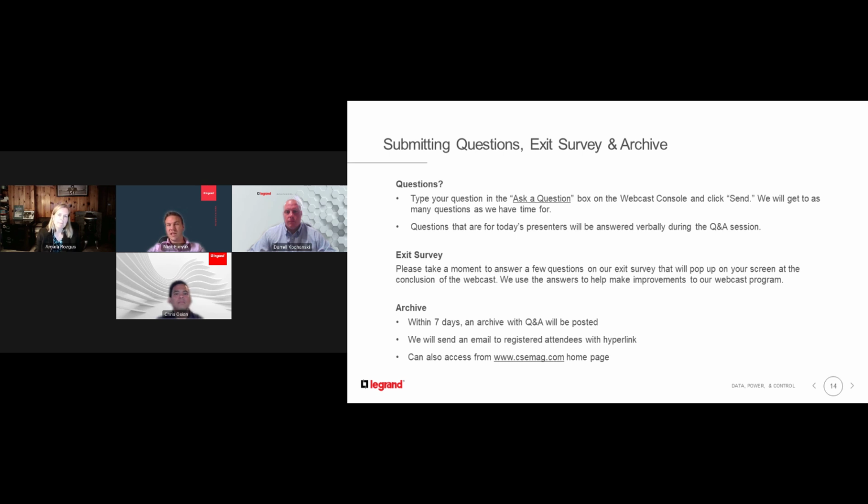So if you say, hey, I ordered a 30-foot run and some changes have been made, and I need to drop this down to a 25-foot run, you cannot cut that in the field. It may seem very easy. We have had guys do that, and I have been on sites where we have tried testing busways out, and we find that they failed.